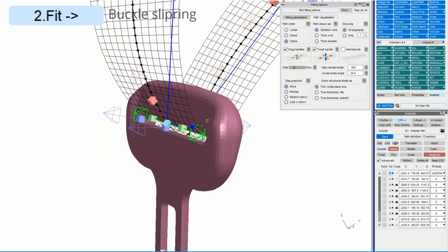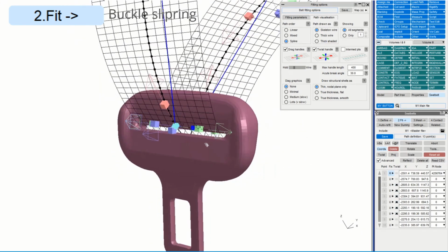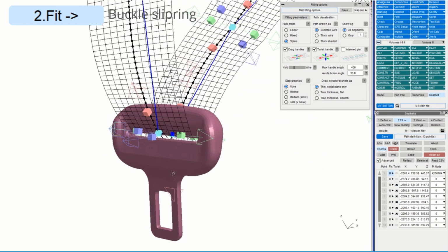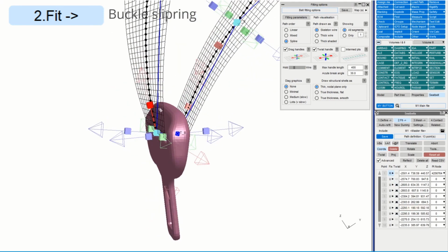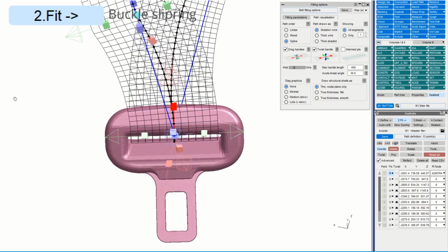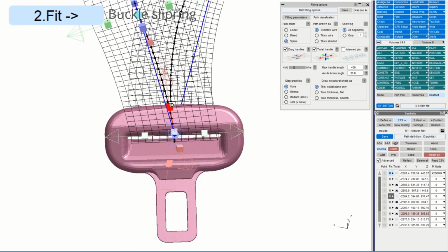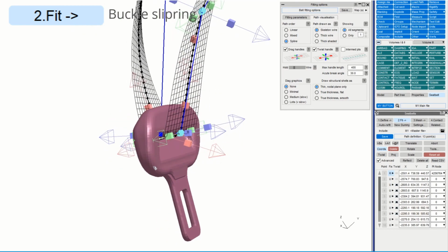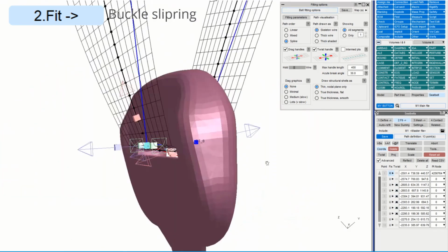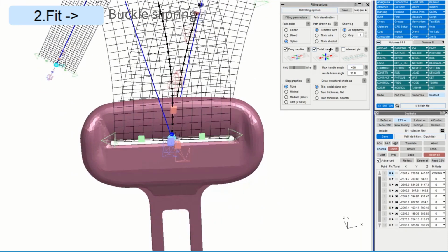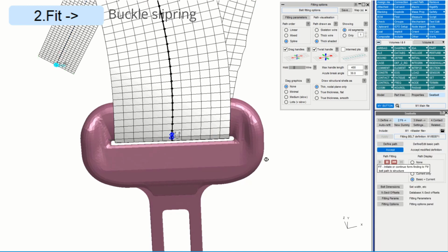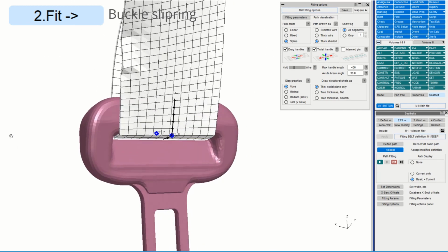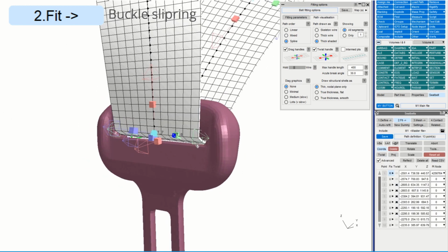Now I can move the red handles to try to fine-tune the belt path either side. Let's lift that up, and I'm going to right click on that red part, and you can see how it deforms the belt angle at that point. Very easy and intuitive after a bit of practice, and that looks like we're nearly done. Let's save and do a test fit. That looks fine. Ignore that kink above that, we'll sort that out later.